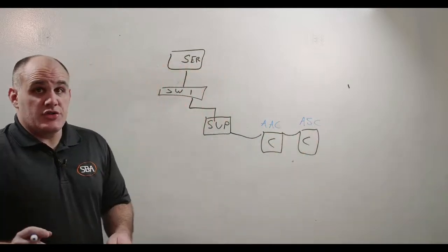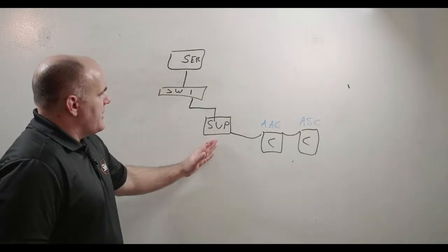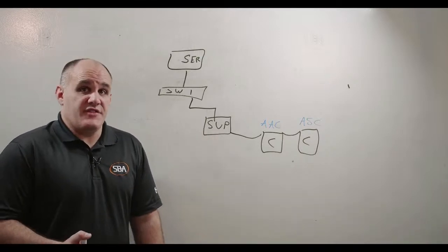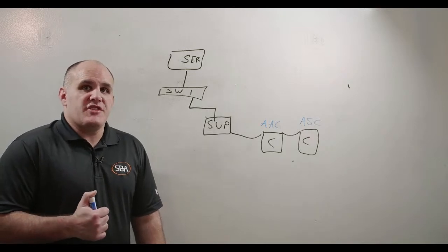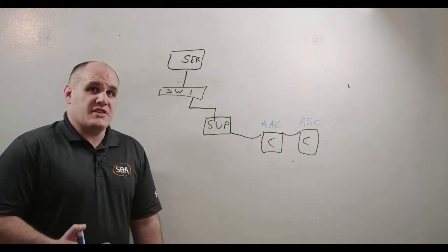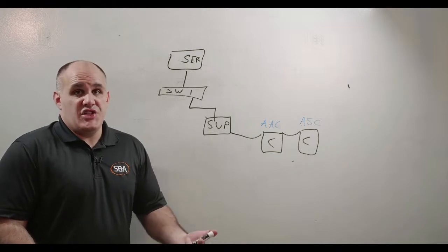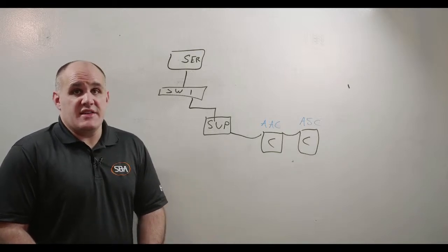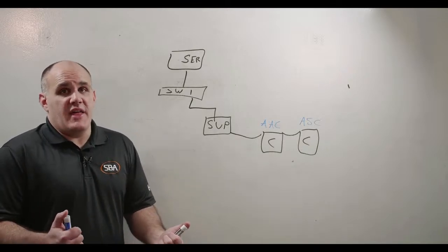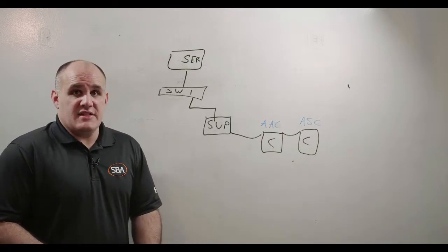So once we've got those two things figured out in our bill of materials, then we're going to focus on our building controllers. Now, building controllers are also known as supervisory devices. And originally, the purpose of a supervisory device was to take serial networks, supervise those networks, and convert those networks into data flow that could be ingested by, at the time, thick clients, nowadays thin clients.